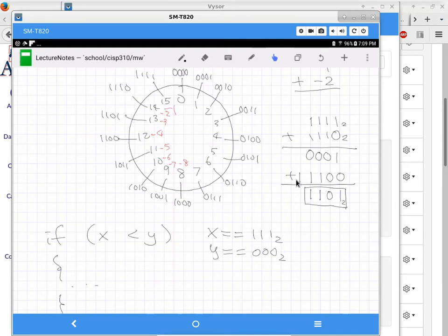The carry in, which is this bit here, is an input pin. And for now, we usually just assume it is 0 because this calculation is standalone. So now the question is, when do we need to attach the carry out to the carry in? If you're only given a 4-bit adder and you want to perform, let's say, an 8-bit addition, how are you going to do it? Yep, you basically want to stack them up side by side so that the carry out of the least significant 4-bit becomes the carry in of the most significant 4-bit. That is when the carry out and the carry in become really important.